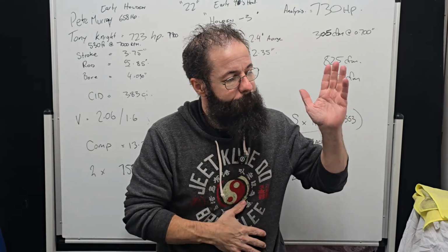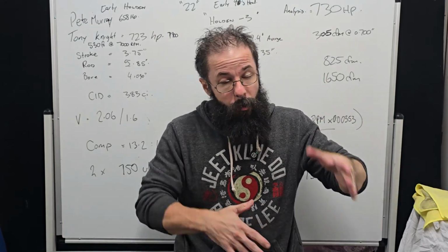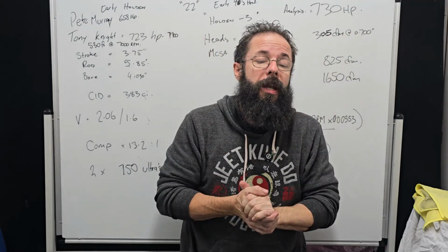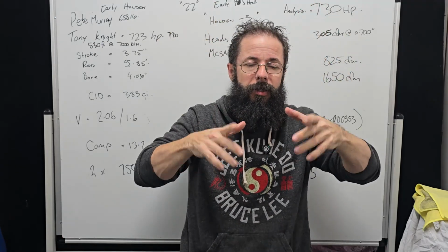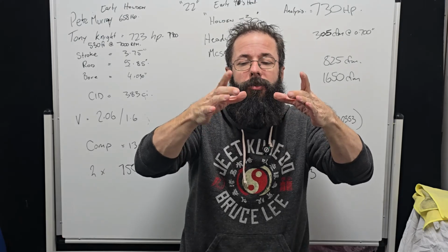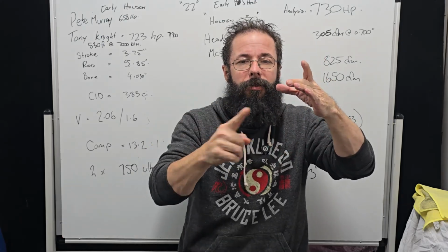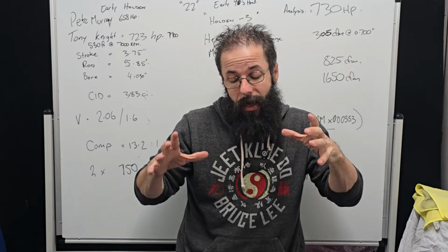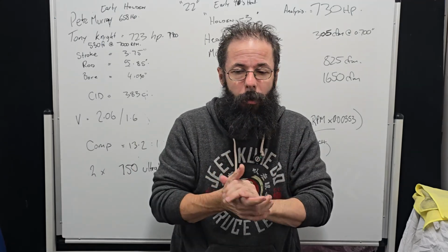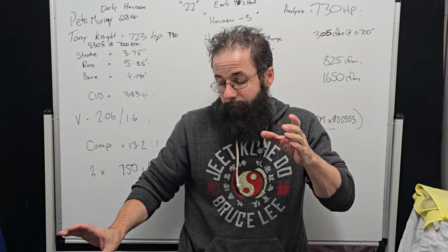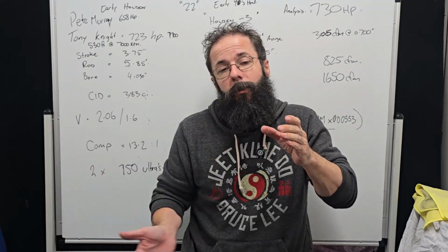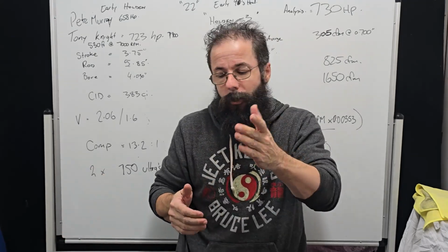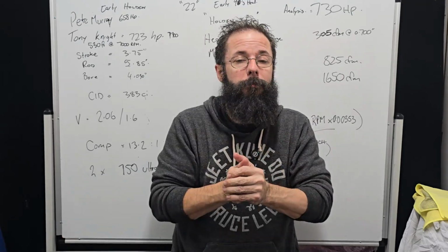But yeah, with the tunnel ram, because we have those negative areas, as the air rushes in on this 4150 flange, we've got all this dead area around the outside, and it acts very similar to what an anti-reversion plate does on a single plane manifold. As this positive wave comes up in a single plane, it runs up the runner and hits the booster.